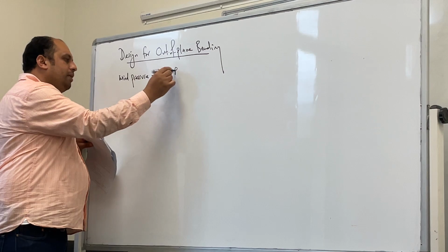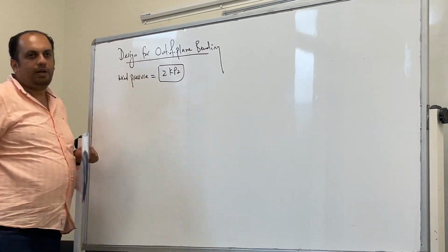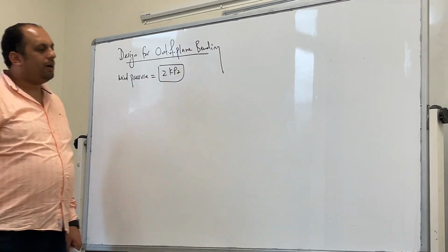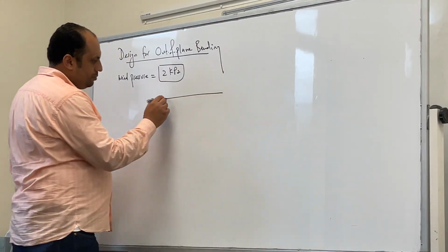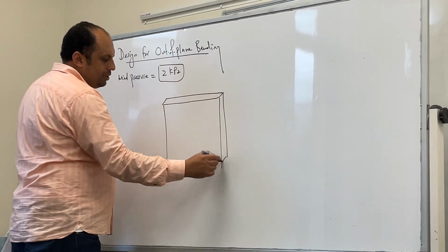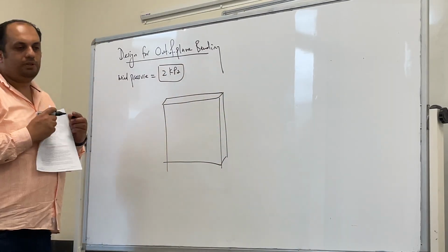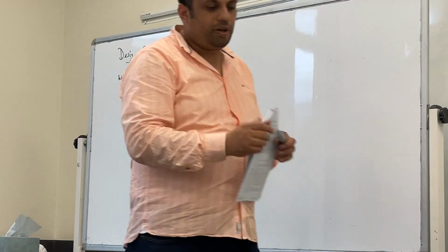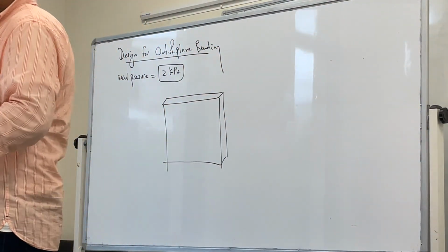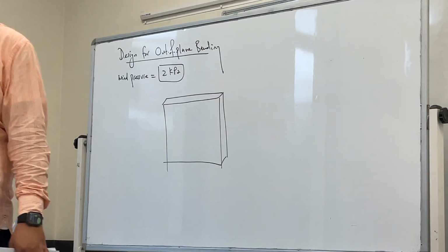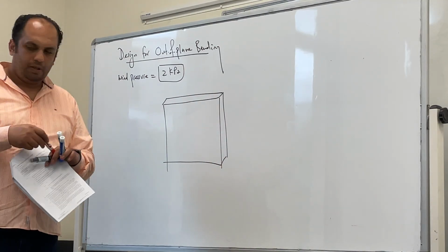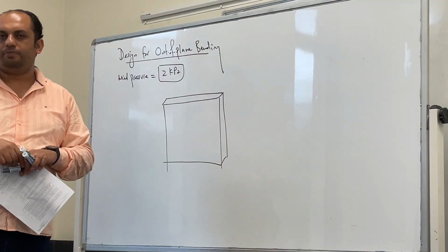2 kPa. Right? What reinforcement did we get from the first part? Just an assumption, or just an explanation of what we got. N12, N12 per meter. So what does this mean? Spacing center to center around 250. Yeah, so this divided by 4.